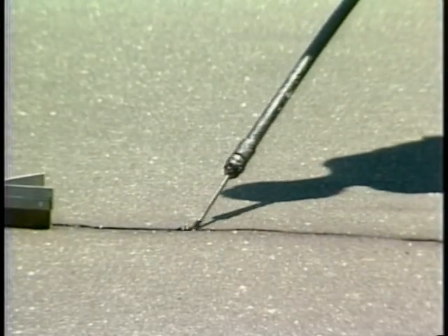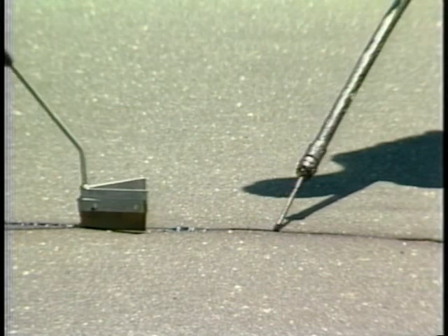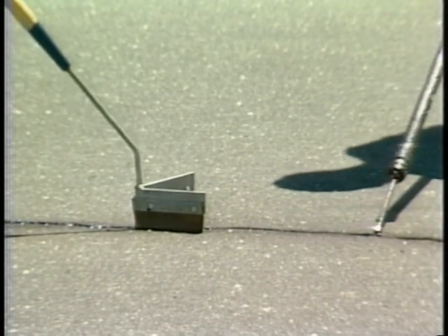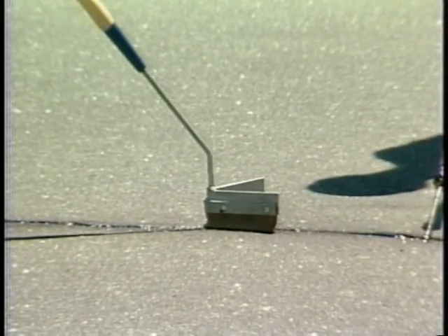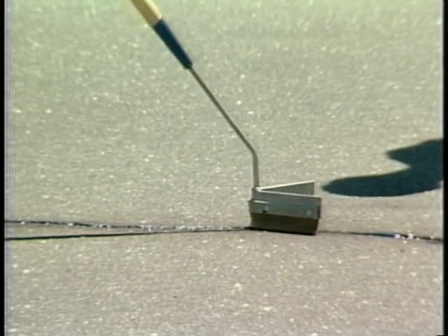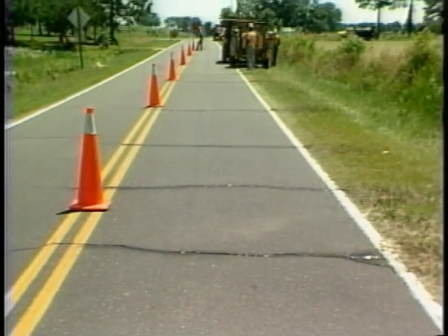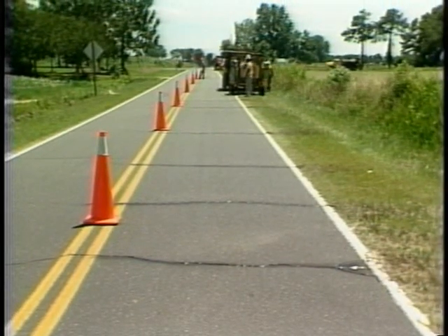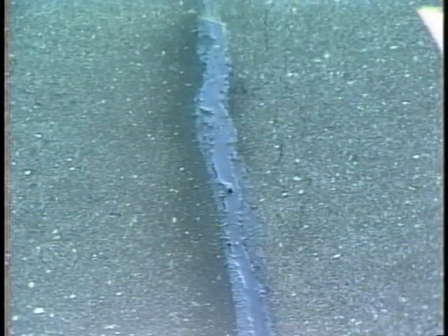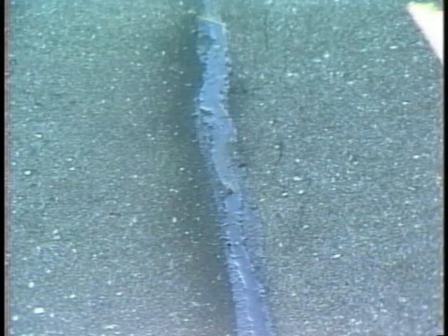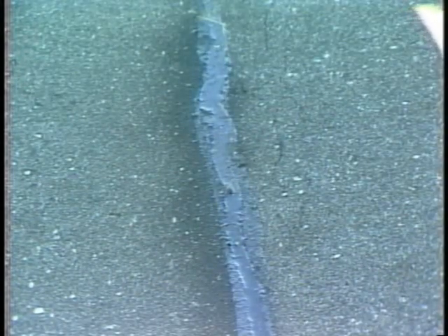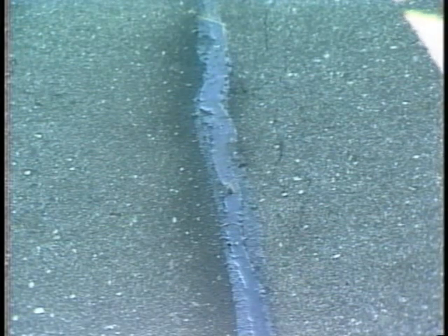This is necessary because the sealant material cools quickly and is difficult to squeegee once it cools. Rubberized asphalt sealants do not require any blotting material after application. Once the sealant has cooled, the road is ready to be opened to traffic. The time required is approximately 15 minutes.